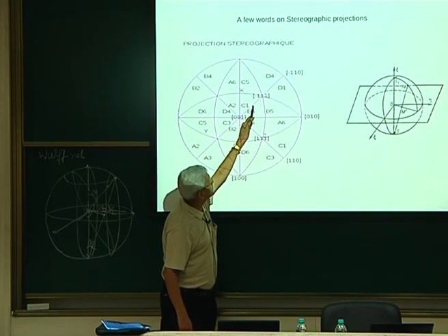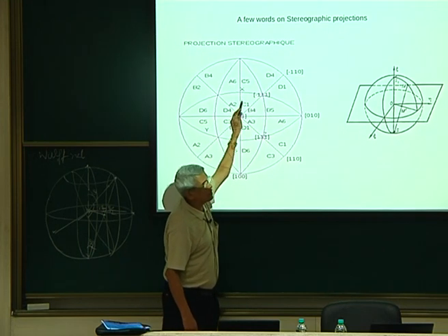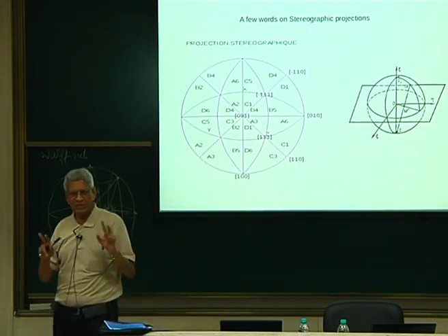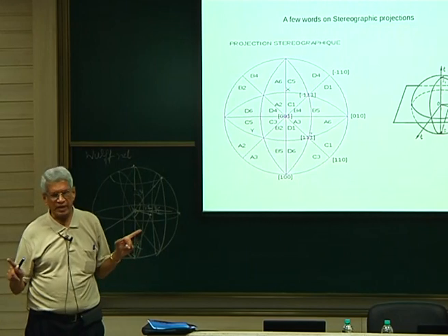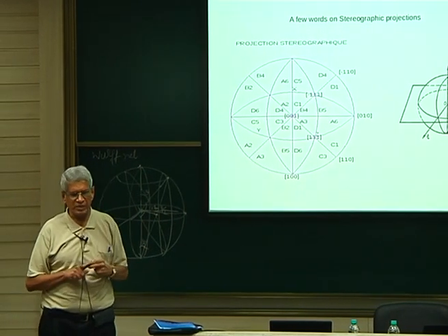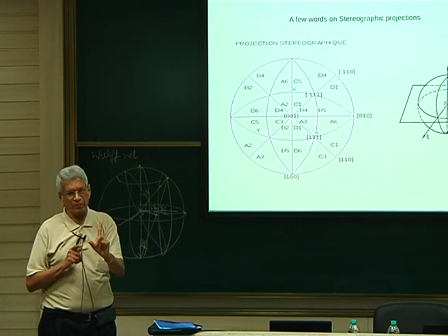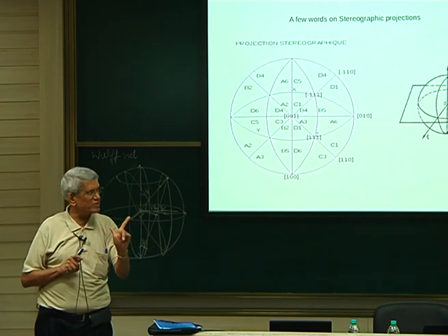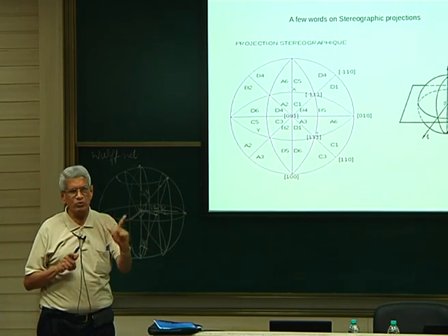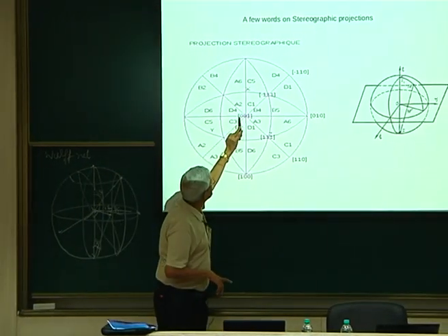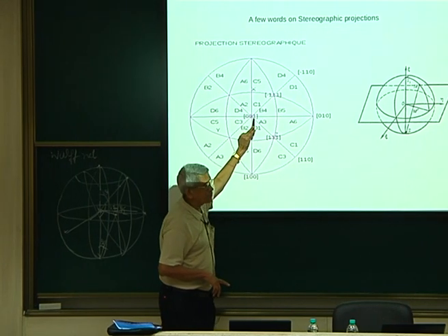So with respect to this, if you see this one as well as this Burgers vector, both are making an equal angle. So two slip systems have got the same Schmidt factor. So both the slip systems will be active. So under that orientation, when the sample rotation reaches that value, then we have two slip systems which are going to be active.